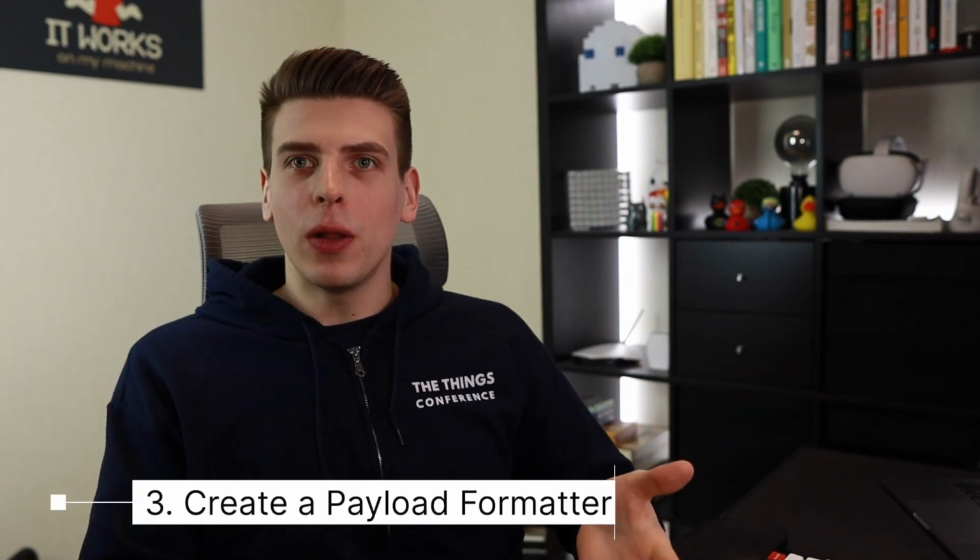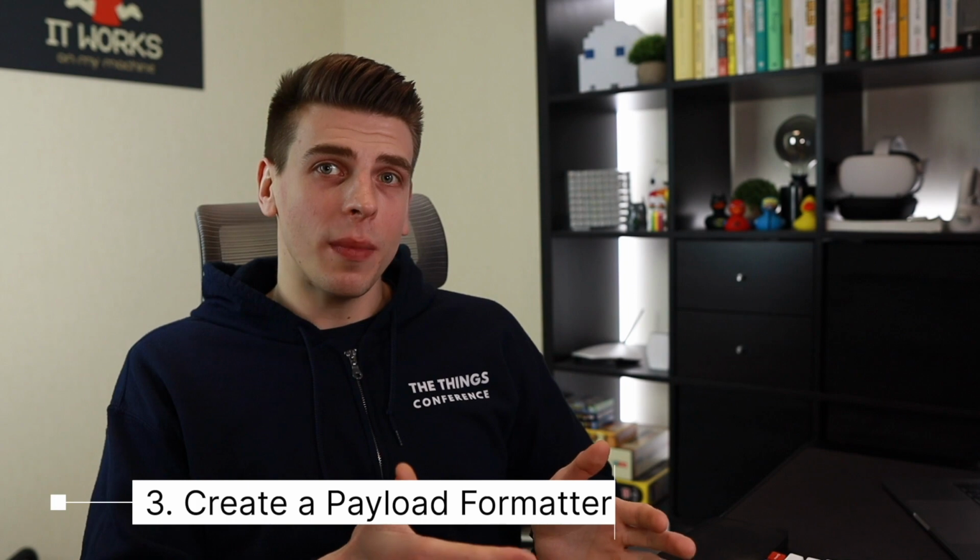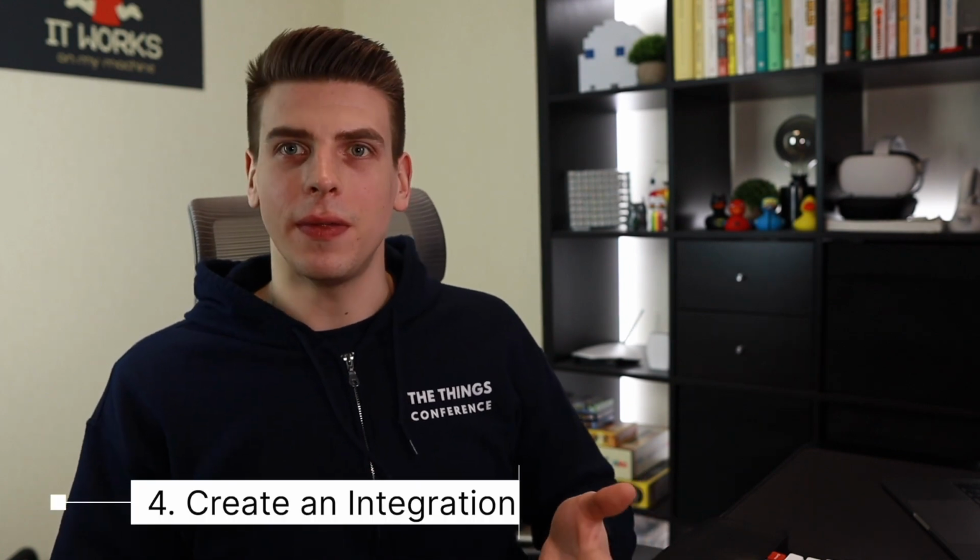Visit the concept of payload formatters. I'll be using a JavaScript formatter to format uplink messages from raw bytes sent by an end device to human-readable JavaScript objects. And discover various integrations that The Things Stack offers that allow you to process data sent from or received by your end device. So first things first, in order to receive or send traffic, we need a LoRa-enabled gateway.